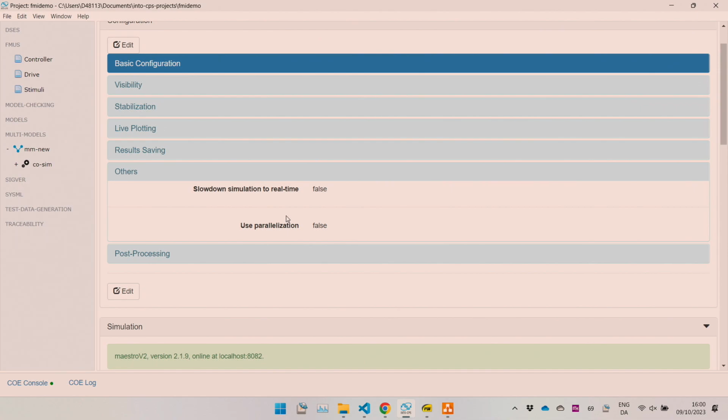So then we have two numerical errors. One is the local ODE error, and then the input approximation error. This error is particularly more acute when you're coupling multiple physical systems, because they will assume that this thing is a constant during this interval. I think Martin Arnold, I don't know if he's come to the conference, has shown a while ago that this input error is the main factor behind the co-simulation error. You can pick whatever solvers internally, that's great, because they typically work in accuracy